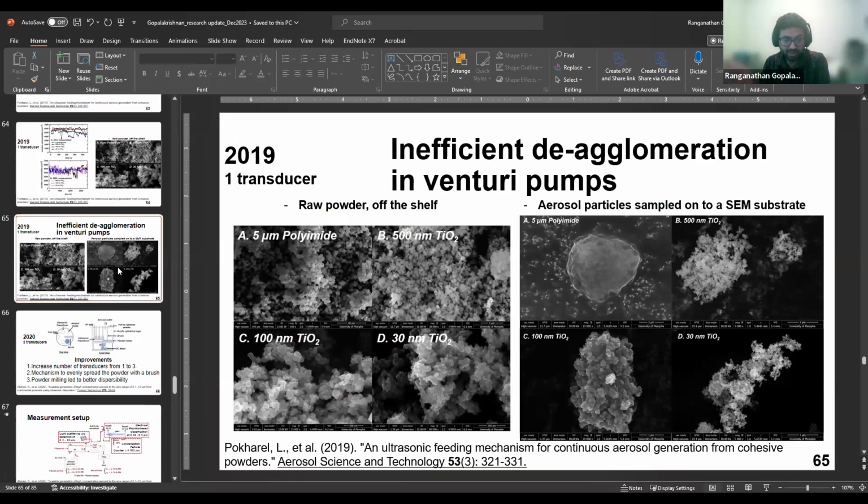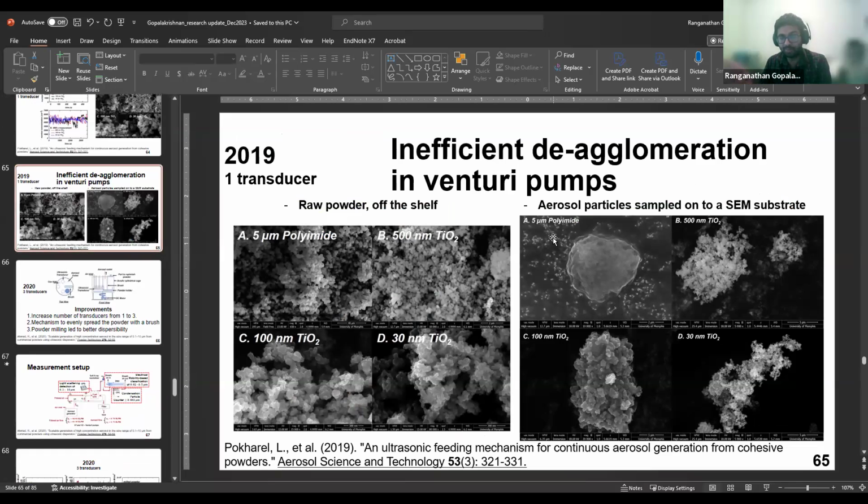Humidity is a huge factor. It can actually lead to clumping, and the dust will behave completely differently in dry and high relative humidity conditions. That is something to be wary about whenever anybody is working with powders, I agree.